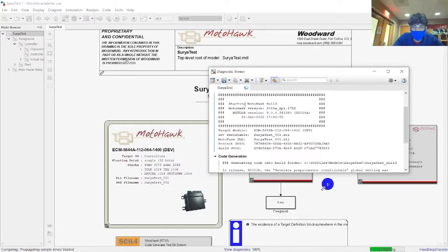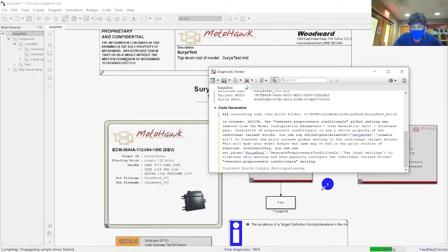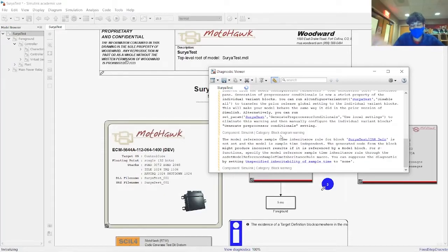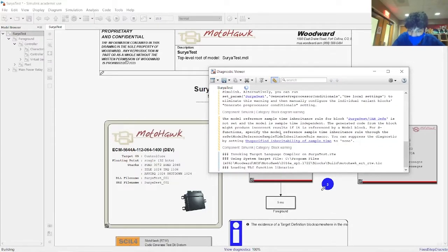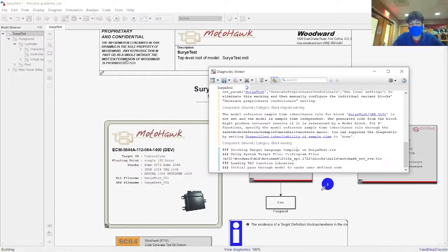So now it's going to generate the code, and you'll basically wait for the Green Hills suite to translate your Simulink code into C code, which is flashed to the ECU. So usually if you have any errors, it won't let you go past this, but there's nothing we've changed essentially, so this is going to compile. Fingers crossed. So just fast forward to this.